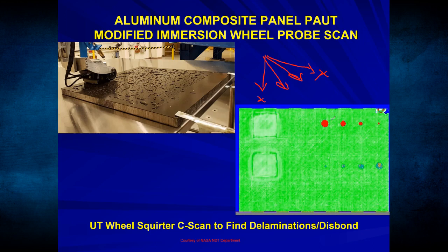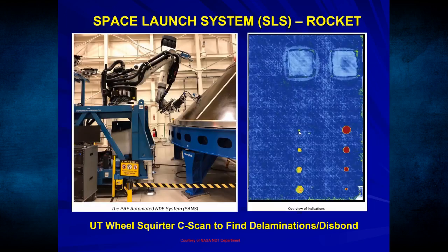So we can find those splices. So this is a calibration standard with flat bottom holes and squares of different sizes at different depths, you see? So using the A scan, B scan, C scan that I just showed you, you can say approximately the depth of those flaws and location.